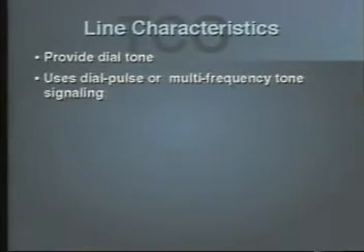Primarily, there's two types of dialing. In the customer premises equipment module, we talk about a rotary dial, or that dial which operates manually. You turn it to an indicated point and you release it. It counts the number of digits that are operated depending upon the number you selected. The other one is called a dual tone multi-frequency, or a push button telephone, where we push one unique button and it generates a series of sounds which the central office receives and interprets as a legitimate number.